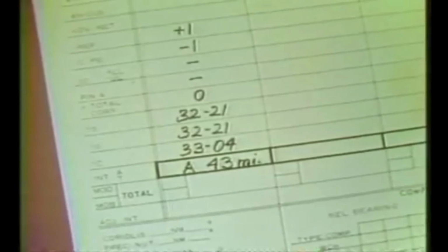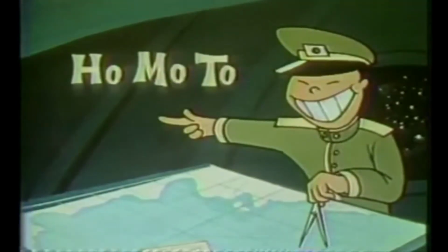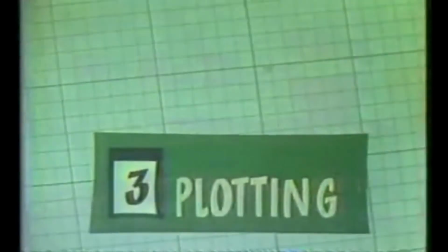By comparing HC with HO, you can determine the intercept distance between your actual circle of equal altitude and that of your AP. Remember HOMO TO. If HO is more, you are toward the GP of the celestial body. With this information, plotting is easy. You have a celestial LOP. With one or more others, you have a fix.